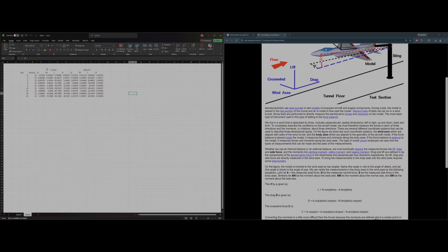And there we go. Now, of course, we can make charts for this. Line integral here. Add x values. I'll just do a simple graph right here. Use these ones here and add. And you can see our data does follow the thin airfoil theory up until about 12 degrees. At 15 it reaches max, and then it starts to drop. This is realistic to the actual airfoil.